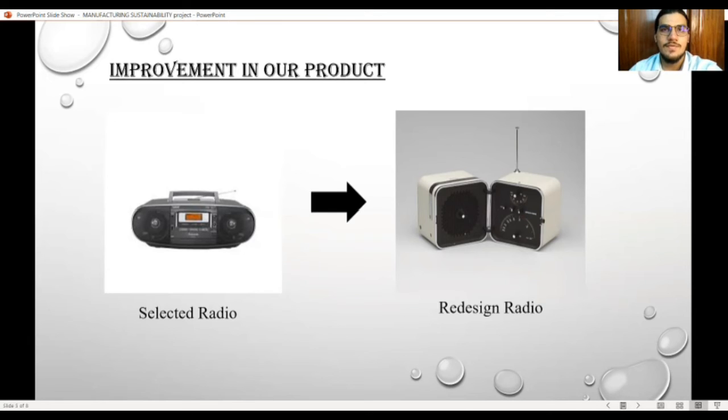For the redesigned product, we changed most parts made of ABS plastic to aluminium. Why did we choose aluminium? Because aluminium looks more premium than plastic. Aluminium is also more durable and better at conducting heat. Many expensive gadgets have aluminium in at least part of their chassis.